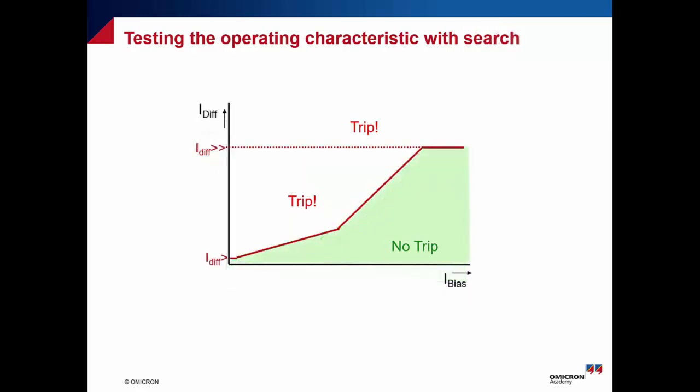Then the second technique we call it search. If you tested the distance protection before, we have also shot, we have also search. The search will look like that. As you see here, if you select the point line, it will go up and down until getting the maximum accurate point, which should be allocated on the line within the tolerance. And for sure, we need to apply at least 2 points for each slope line to verify that the slope is correct as we are setting or not. This is how it is working in the search technique. And for sure, if it is within the tolerance, it should be passed.